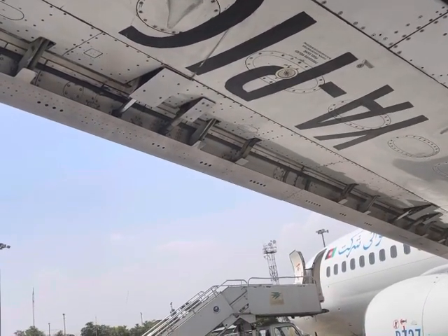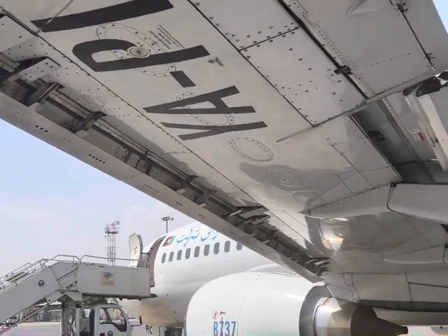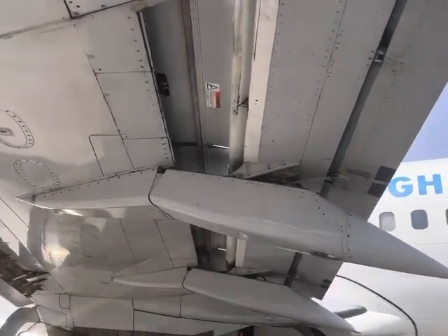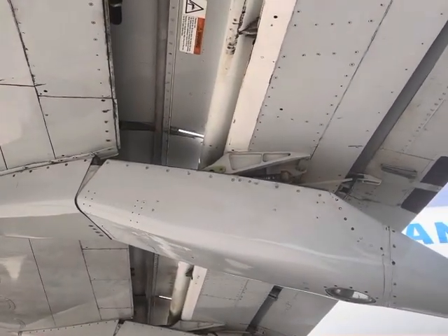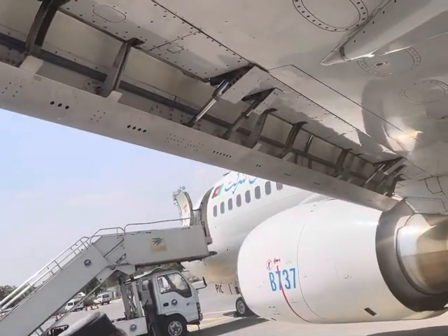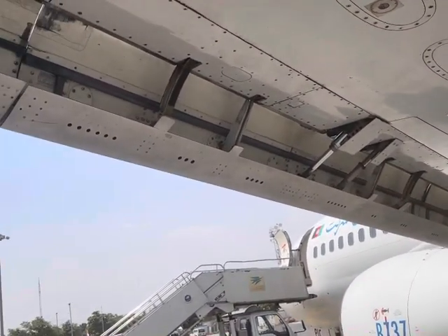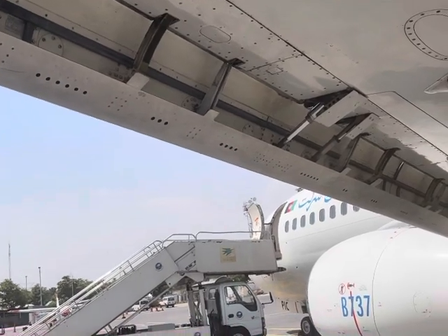Extending the trailing edge flaps up to 5 degrees will extend the leading edge flaps to full extent because they have only one position, but will extend the leading edge slats to the extended position, not the full extent. So we have one position more for the leading edge slats, which is the full extent. If we move the trailing edge flaps beyond 5 degrees, then the leading edge slats will be moved to the full extent position. There is another automatic system which will move the leading edge slats to the full extent position.